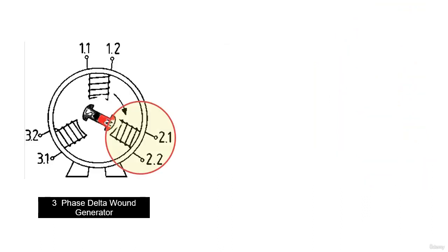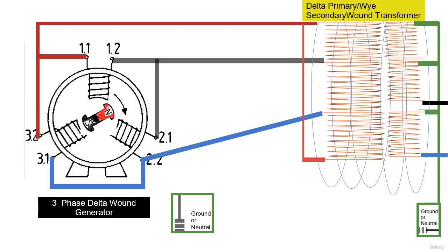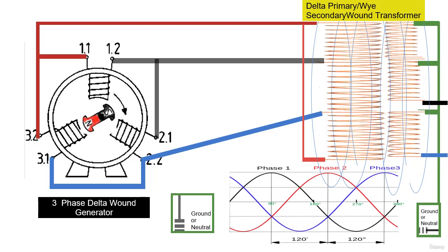If we added 2 more coils, then we would have 3-phase. And again, to simplify, let's say each phase creates a voltage difference of 120 volts AC to ground or neutral. 3-phase is created because the magnets are passing the coils at different times, creating peaking waveforms or peaking voltages at different intervals. This is what out of phase means.